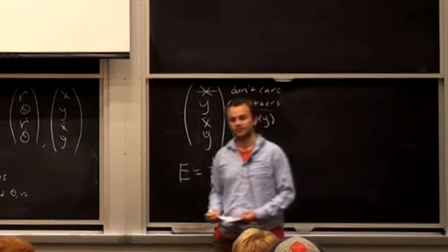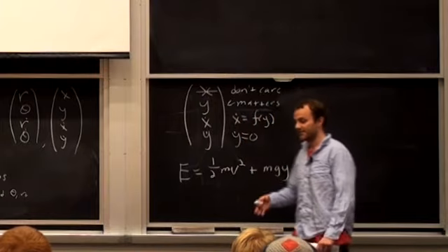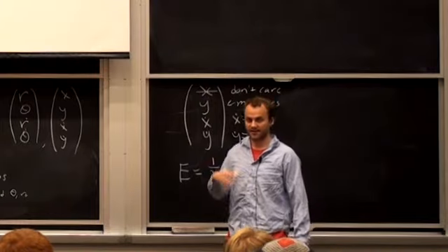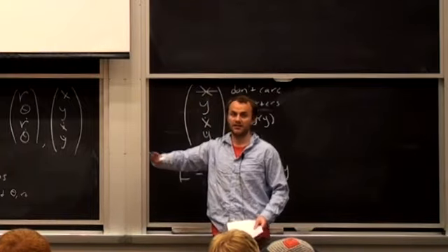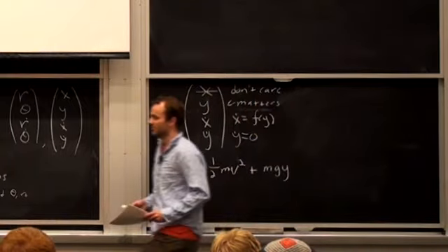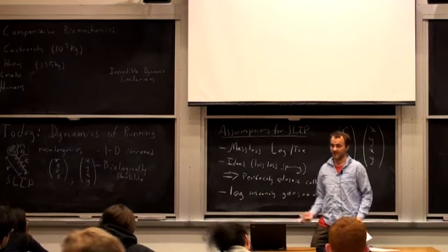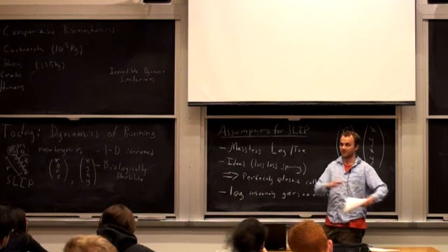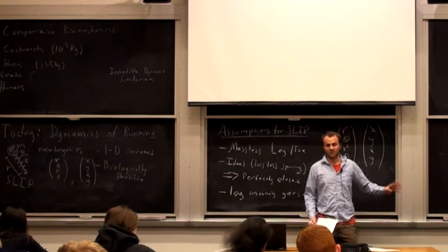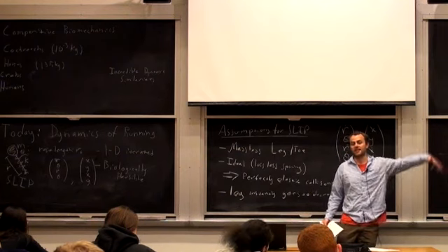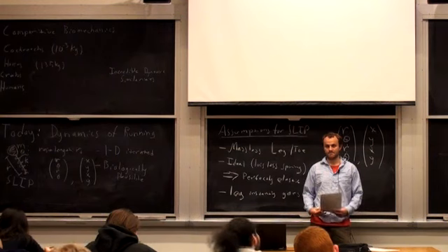Why don't you care about x again? Because that doesn't affect the stability of the system, right? If we're trying to get somewhere, hit a target, then we have to look at x in our controller. But because x doesn't figure in the dynamics anywhere, it doesn't matter. Sorry, this is something I probably should have mentioned in the beginning. It's not going downhill or anything like that, right? So how far it goes in x doesn't matter. The dynamics are going to be the same, invariant to that. And so x will be changing, but it won't affect the next apex height because it doesn't figure into the dynamics like that. Does that make sense?